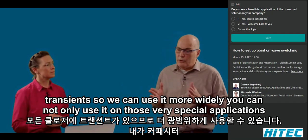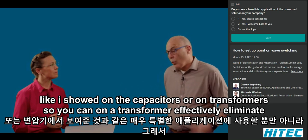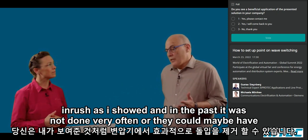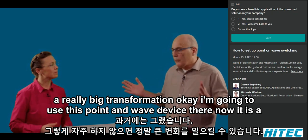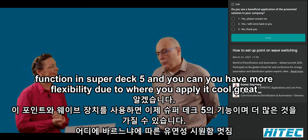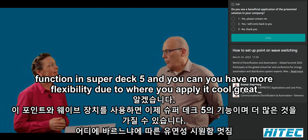You can not only use it on those very special applications, like I showed on the capacitors or on transformers, where you can effectively eliminate the inrush, as I showed. In the past, it was not done very often, although for a really big transformer you might say, okay, I'm going to use this point-on-wave device there. Now it is a function in SIPROTEC5, and you have more flexibility in where you apply it.